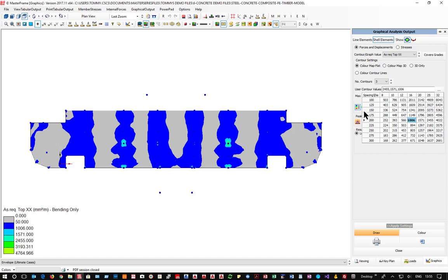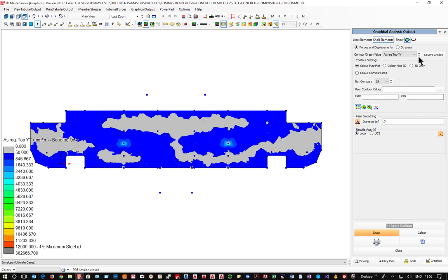So I don't need more than 16s at 100 except in these very high intensity areas, which I will then, because that's a point load, so we need to get some additional rebar in this direction to support that, and likewise at these values. That's X. Y is sort of similar.